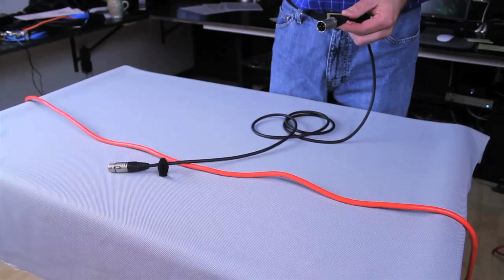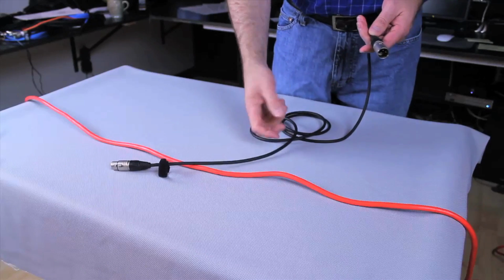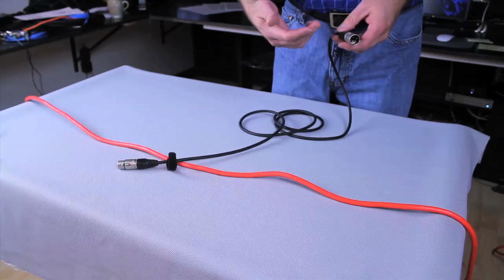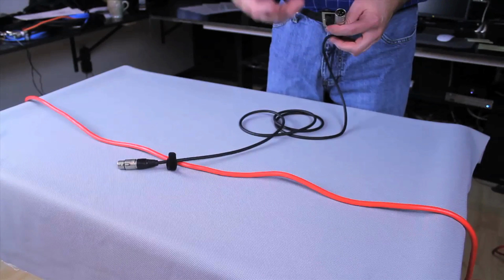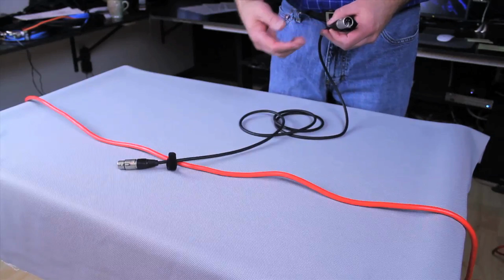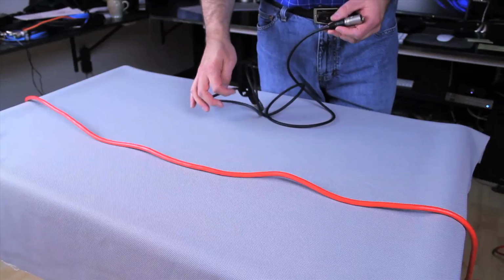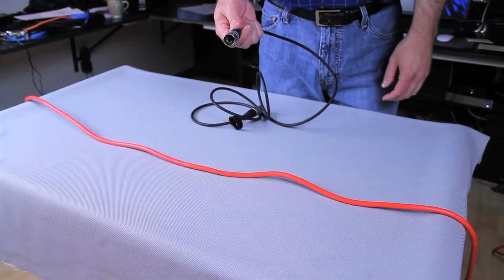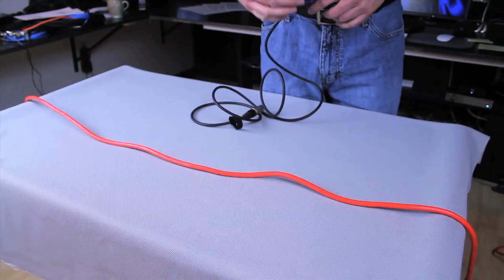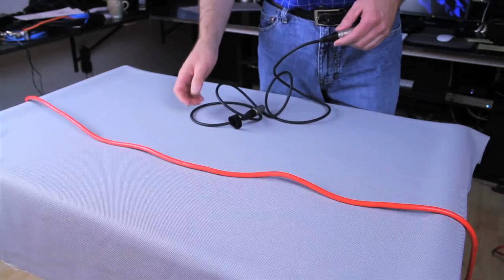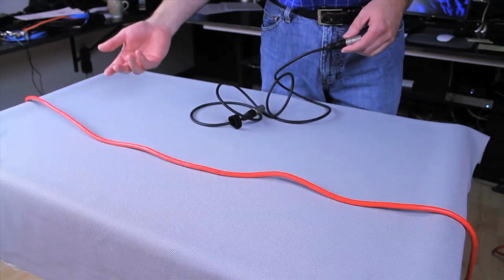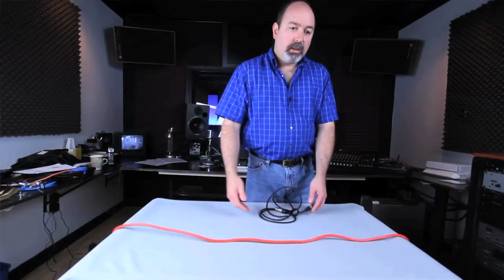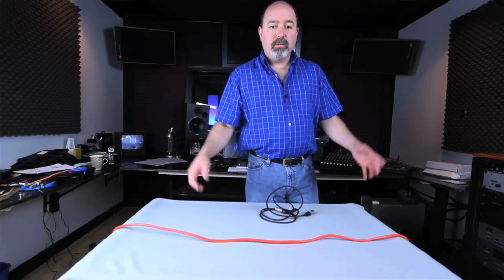Just get in there and clip it, sacrifice that cable, and then that one is in your kit all the time to fix those problems. You do run the risk of the audio being a little bit thinner sounding, possibly, and there may still be some buzz in there, but a lot of times it knocks it down completely. If the buzz is still there, you've done your jack in the wall, you've clipped this, you may have some other shielding problem in one of your cables. You just have to go through one cable at a time, pull it, replace it with another one. That's why it pays to take extra cables with you. That's it for the grounding. That's it for cables this week and connectors.